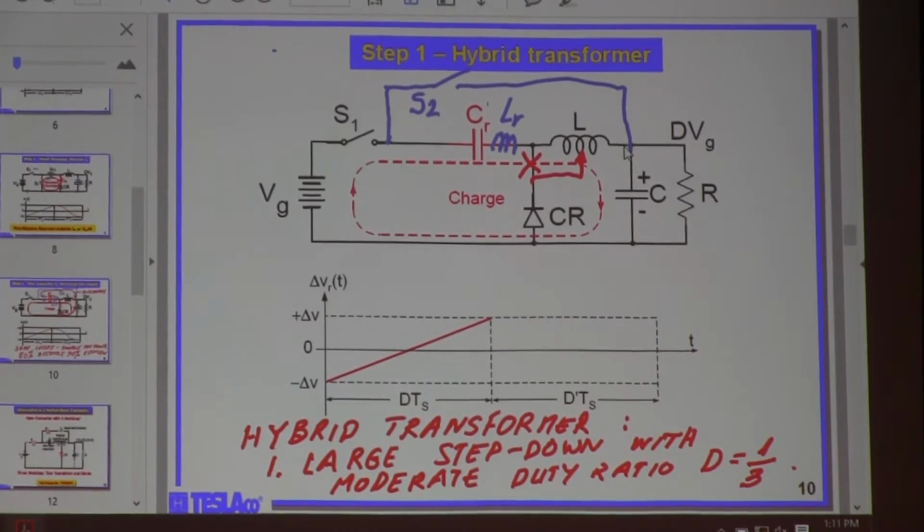So what happens if this is one turn? That's what I said before, but it's not obvious. If this is one turn and 100 amps on the output, because that's the only thing connecting to the output. Plus, there is some help from here. But let me tell you, this is not any more important. Can you see why? When the turns ratio is 10-to-1 here, is it important? Because this primary current, because it's a 10-to-1 step down in the voltage, but it's a 10-to-1 step up in the current. So that resonant current on the primary is going to be 10 times smaller than the current already coming in here. So I'm adding 1/10 of a current extra.